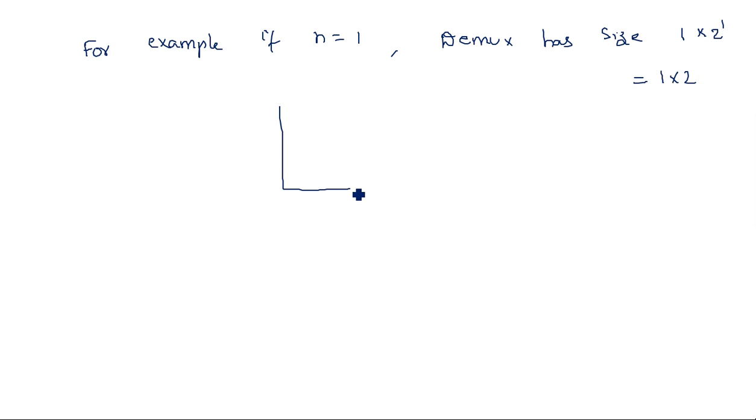So we have one input D and two outputs. How many selection lines? N is equal to 1 means the number of selection lines is 1. So the output lines are O0 and O1. This is the 1 by 2 demux, the demultiplexer with 1 by 2 size.